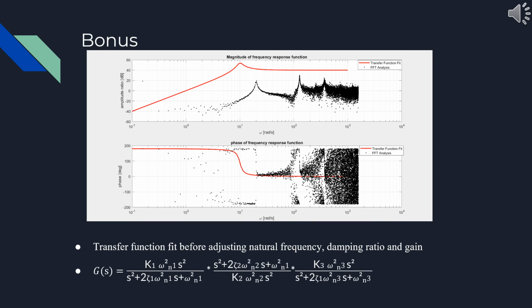In order to mathematically encapsulate the transfer function which can describe the data up to a frequency of 30 Hz, we need to multiply the individual transfer functions. But in the second term, we note that the numerator and denominator have been inverted. The reason for it is because the second peak is in the inverted direction as compared to the other peaks.